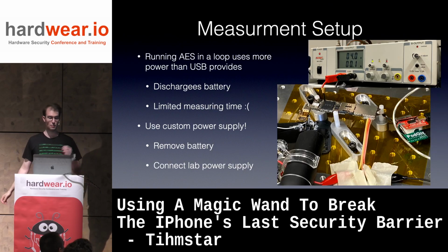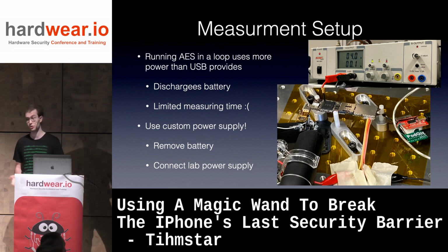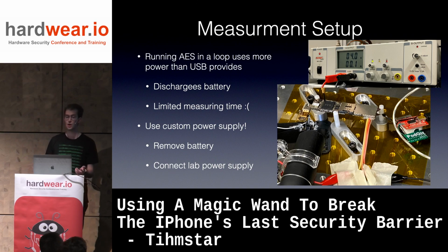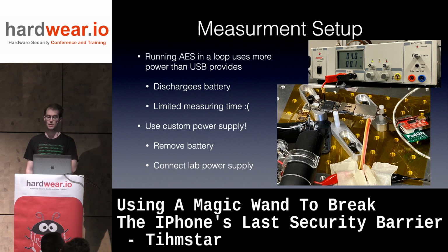Measurement setup: well, running AES in a loop uses more power than USB provides, which discharges the battery, and you have a limited measuring time, which kind of sucks. So just remove the battery and use a custom lab power supply, and solve the problem. Easy.